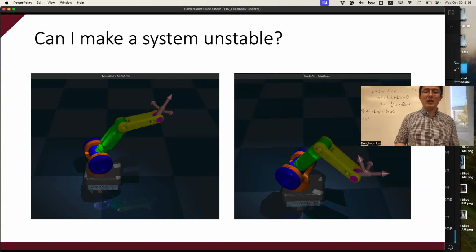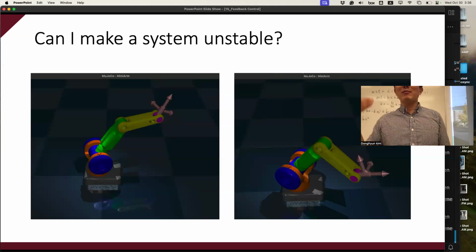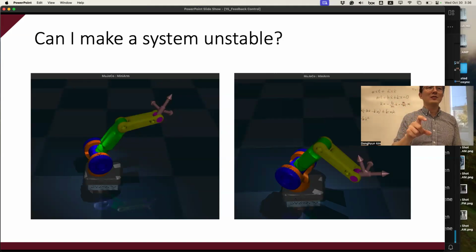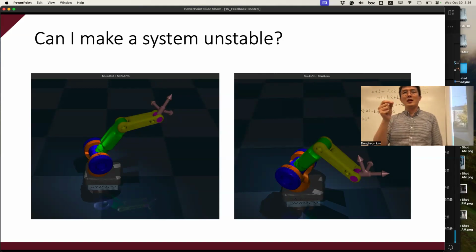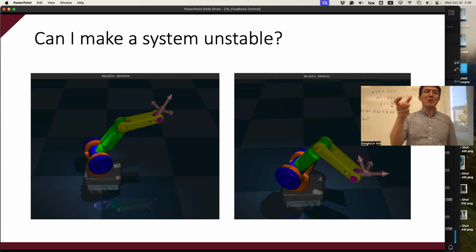And this digital simulation is actually not even close to the real world continuous dynamics. So the sensor data you've seen is at maximum 1 millisecond old, and the control input you can engage is going to be applied to the system after 1 millisecond. So there is the time delay. If the time delay gets bigger and bigger, then the system can be more and more difficult to control.